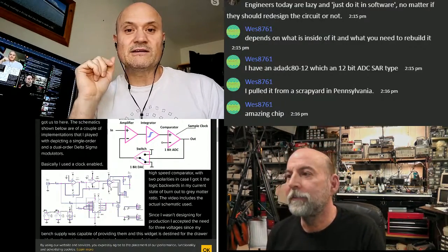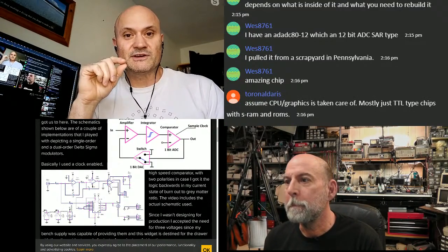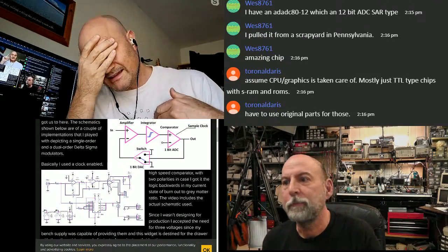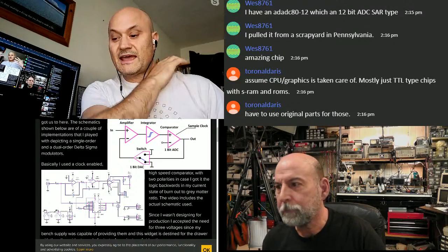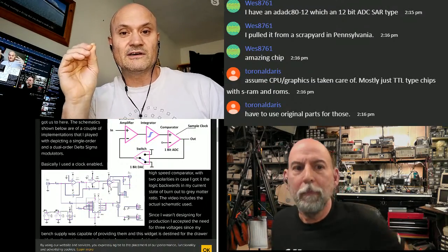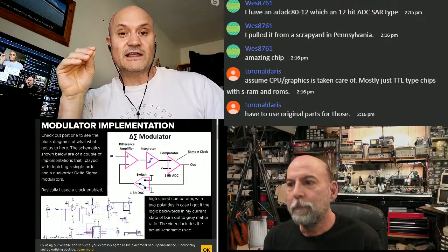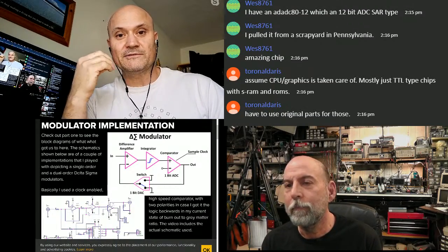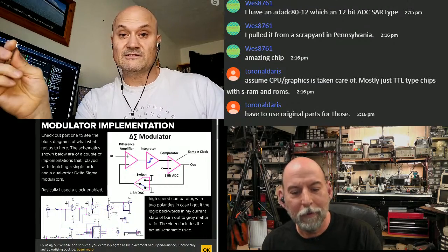The only way they did it was because they used the analog circuit in front of it, they used the compander. They used the compressor in the front and an expander in the back, and they did very, very careful analog circuit and PCB layout. The board's only 2 layers, so they don't have ground planes everywhere. They had to be super careful to not have problems with noise. And the unit just sounds amazing, and it's very low noise.